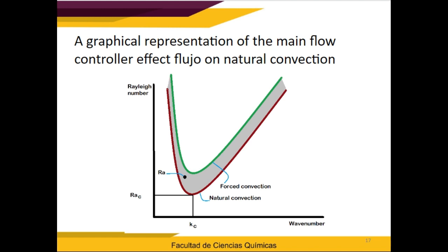Also, this approximation to the control of convection in a fluid layer is another option to the strategy based on modifying the perturbed temperature boundary condition as done by other researchers. Finally, as a side comment, more realistic results could be obtained from a cascade control approximation by combining top wall and temperature at the bottom control signals.